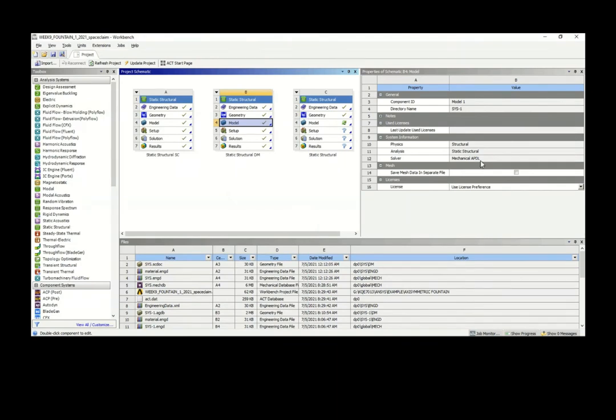So that is about this case study where we cover two-dimensional elements, especially axisymmetric problems. Here we are also dealing with adaptive meshing, which helps us to refine our mesh so as to get more consistent results. Like in this case, we get a more accurate result because we have a final mesh and it converges based on the 1% total displacement deformation between the previous iterations that we have set.